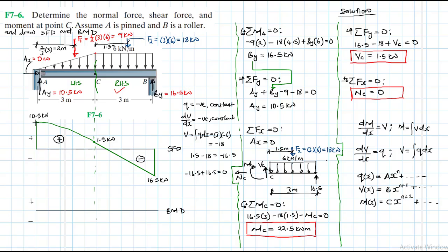We have that point, which is a 10, and that one is a 16. We'll be mindful about this distance. Let's find this distance in advance, because we'll need to calculate it to help us find the maximum value of the moment, because we know that we have the maximum value of moment where we have shear equal to 0. So let's find that value quickly.